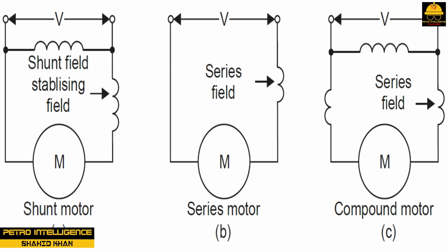There are three basic designs for DC motors: series, shunt, and compound. The difference between designs is due to the circuit arrangement at the field structure and armature. Series motors are connected in series at the armature and the field magnets. Electric current flows through the field magnet and into the armature. Series motors are characterized by their ability to start up quickly. Motor speed is affected by the size of the load.